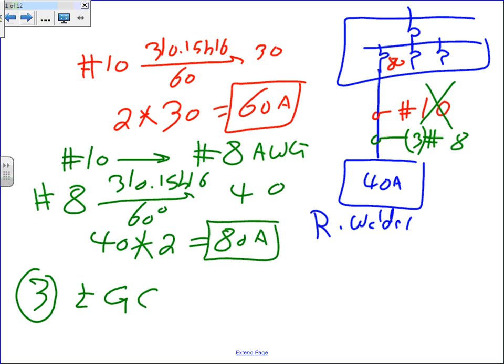Does that make sense? So always size based on the conductor, basically. So put a larger one from the far end and make it instant trip, then it would have some effect. Correct. You don't want to go there. You just size up your conductor. Yes, William? I was going to say, if you put something in there, would you have to up the size though? If you put one here? No. If you lower this to 60 and put the 80 amps here, then you don't have to up the conductor size.